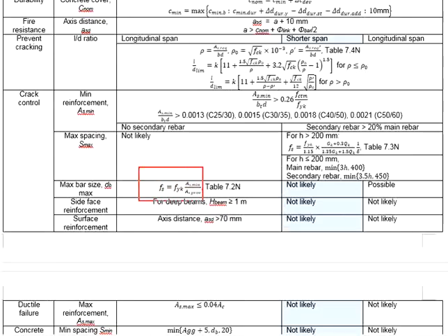This formula is used to determine the stress in the reinforcement. It is defined on the basis of the fyk as well as the ratio between the As,req and the As,prov. The maximum bar size is likely an issue to RC beams, but not likely to the slab.